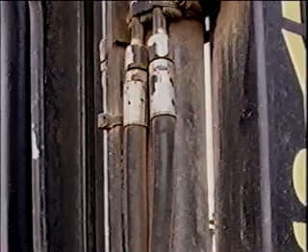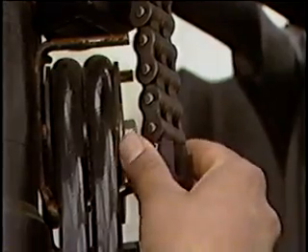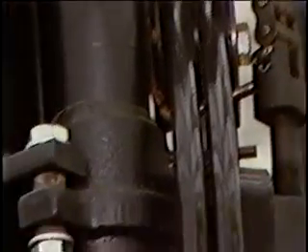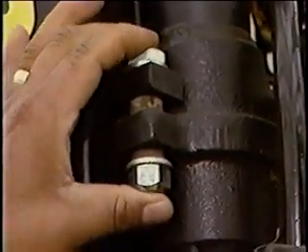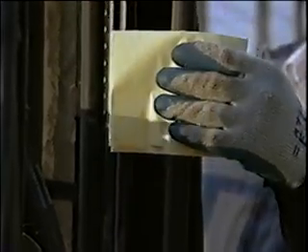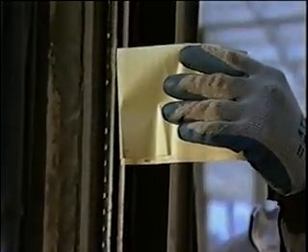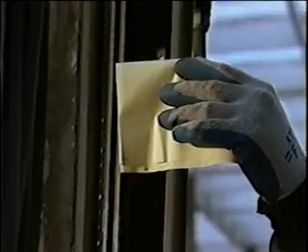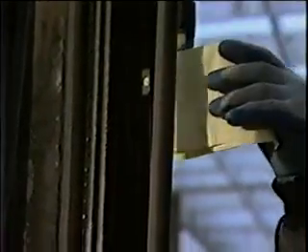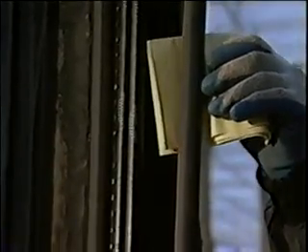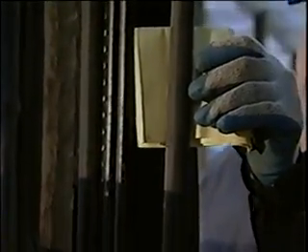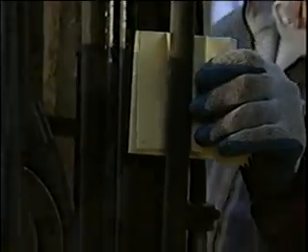With the forklift shut down, visually check the condition of hydraulic hoses for pinch points and worn spots. Check chains, making sure the cotter pins are in place, and make sure carriage bolts are secure. Then, with the forklift turned on and under pressure, check the hydraulic hoses for fluid leaks by running a piece of paper over all the surfaces of the hoses. Never use your bare hands to do this.